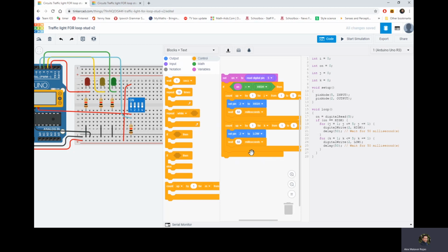All right, so basically we are going to switch on these instructions by moving the switch in here. Then we turn on the red LED for 5 times by 50 milliseconds. Then we jump into the next instructions. In the next counter, we are going to switch off the LED for 50 milliseconds 5 times. That's 250 milliseconds. And then we keep asking.